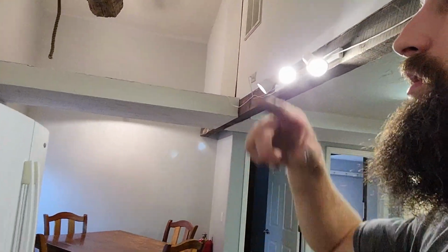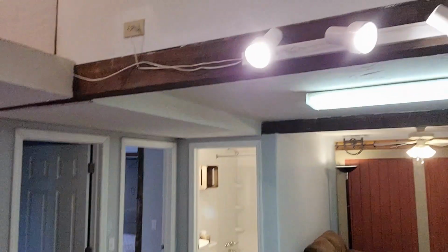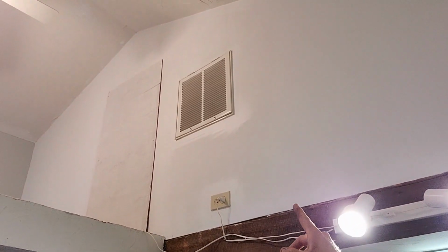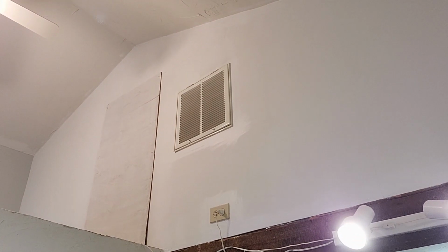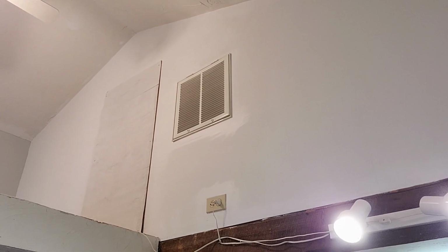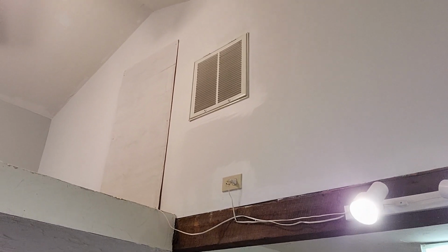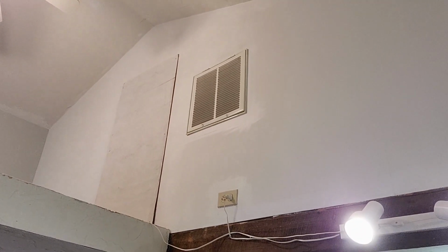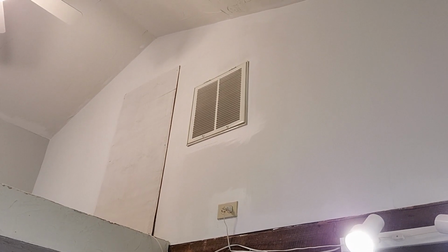I don't think there's a whole heck of a lot of insulation sandwiched between the drywall and the underside of those shingles. I can tell you that right now. There's not a lot of air movement up there, there's not a lot of insulation, it gets toasty. So we want to know that. That's a good question to ask the homeowner: do you have any area in your house that gets abnormally hot?